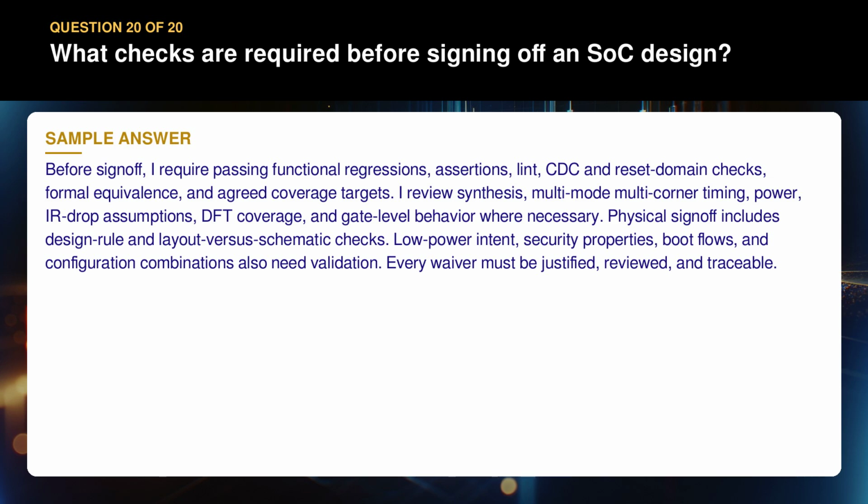I review synthesis, multi-mode multi-corner timing, power, IR drop assumptions, DFT coverage, and gate-level behavior where necessary. Physical sign-off includes design rule and layout versus schematic checks. Low power intent, security properties, boot flows, and configuration combinations also need validation. Every waiver must be justified, reviewed, and traceable.